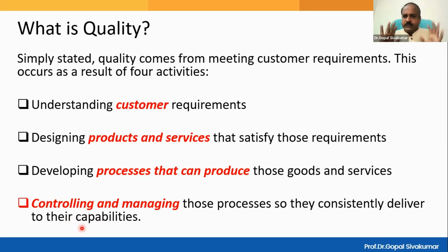Hope all of you will be doing this. You will be collecting some data. You will be plotting a control chart every day while starting the shift. You will do certain checking on the shop floor, whether the settings are okay, whether the operator has come on time, and all those things you are checking. Why? Because you want to have control over your quality. Sometimes what happens, an improvement will be required. Improvement is required if your process is designed badly.